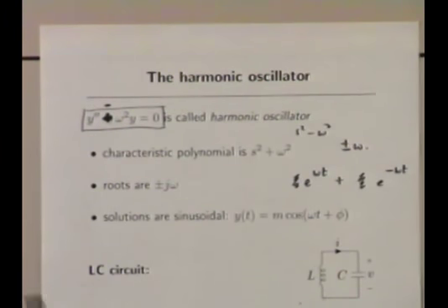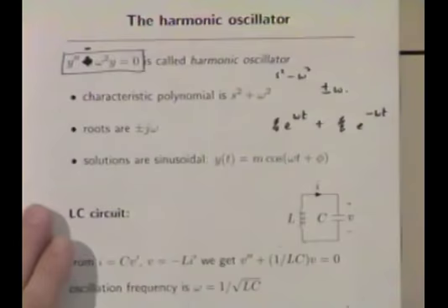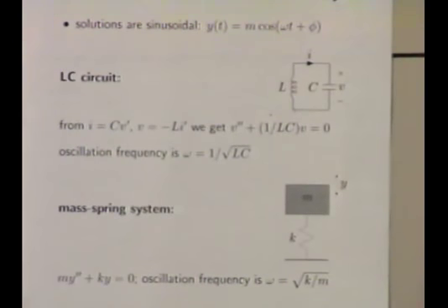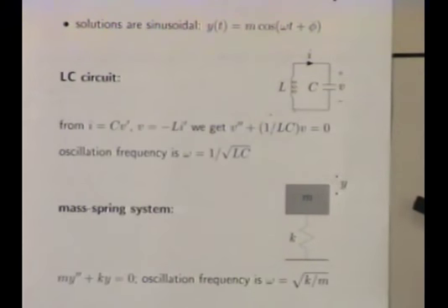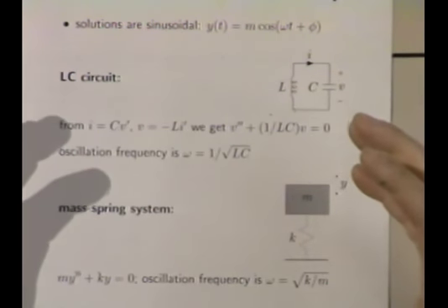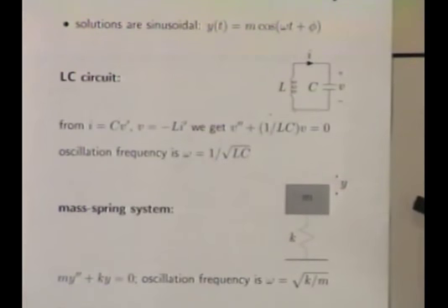And in fact, you can easily give simple mechanical interpretations of it. When you change the sign here, on a mass spring system, that's the same as finding yourself a negative spring. What's a negative spring? Well, a positive spring is where when you extend it, it pulls back. A negative spring is when you extend it, it says, oh, no problem, and it pushes you farther away.